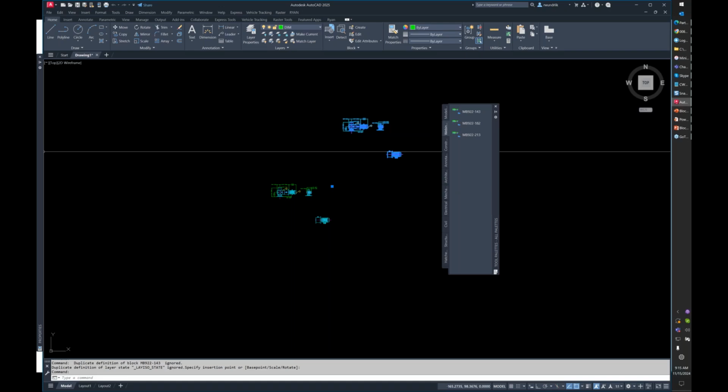Let's see, do you know why sometimes I have blocks in my drawing and when I open the drawing later, it will say the drawing needs recover? I recovered and it solved some issues and deleted all my blocks from the drawing. Yes, Wendy. Generally, that means that the block definition that you brought in has a corruption of some kind, or your drawing that you're bringing it into might have some problems.